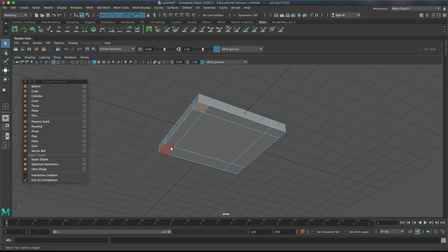All right, so we're going to select these 4 corners. The way I did that, again, we're in face mode, and I hold shift, which allows me to select those 4 corners. Now if I don't hit shift, it'll just naturally select the next one and override the first one. So make sure you hold your shift, which will make that plus sign on your cursor.